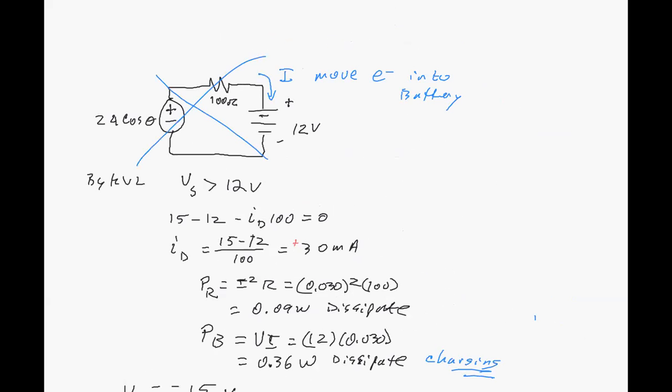We need something that will limit the voltage going into the battery so that it's always positive, even though the voltage on the battery will change over time. As it charges up, the voltage in the battery is going to go up. It's going to be 12.5, 12.6, up to close to 14 volts. It's always going to be going up, and this AC power supply needs to adjust and always be able to charge it. It could start as low as 3 or 4 volts, but it's going to go up. So we can do that with a diode.